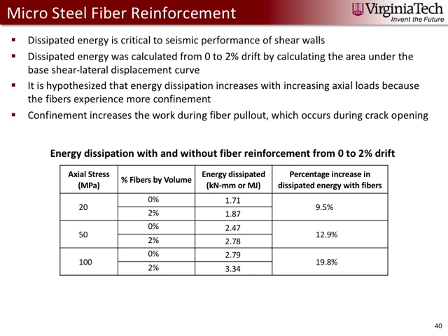So with crack opening, the fibers bridge the cracks, and as they open further, they're pulled out. Confinement on these fibers increases the work during fiber pullout, and in turn increases the dissipated energy during lateral loading of the wall.